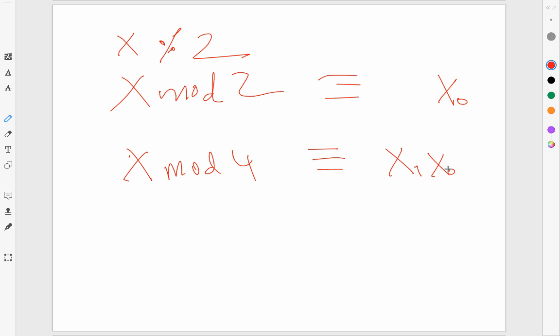Let's see what else I wanted to say. Okay, finite state machine questions. One of the questions is about transitions. The transition being referred to there is a transition on the data input line, and specifically the state machine is observing the input at every clock tick. If it's a Moore machine, then at every clock tick, whatever the input value is at that time gets used to define the next state. So when we are talking about a transition, what we are really saying is that the input was 1 and then became 0. In one clock tick I saw it as a 1, the next clock tick I saw it as 0. So that's what happened.